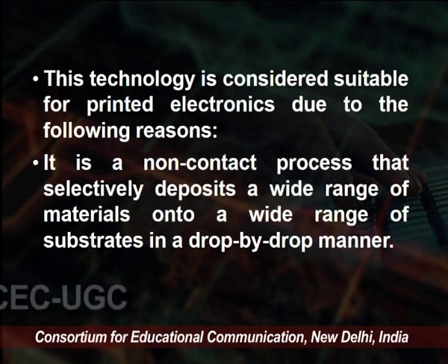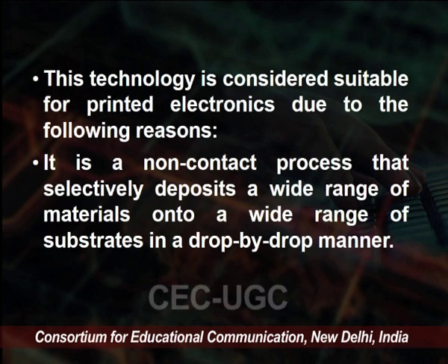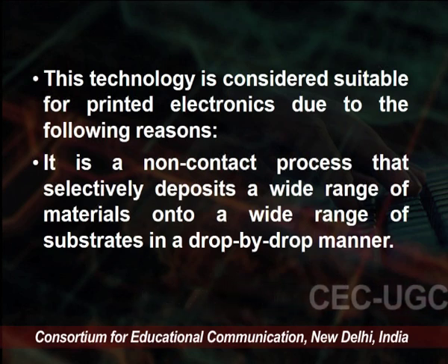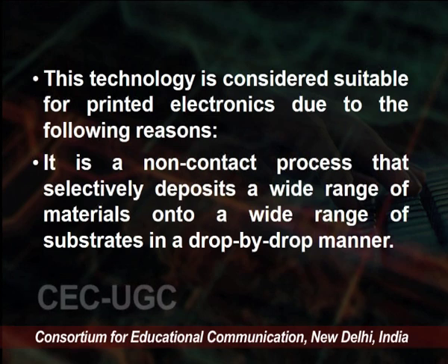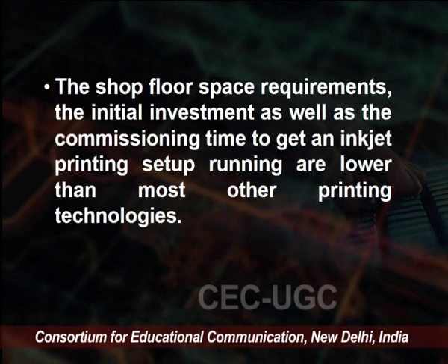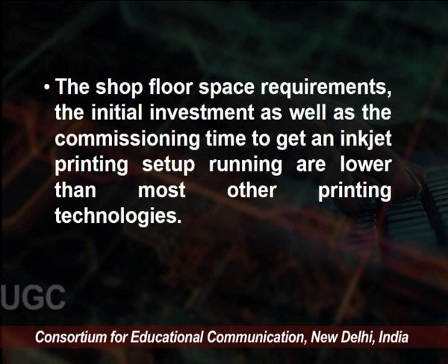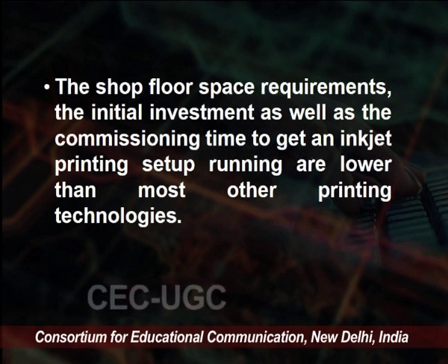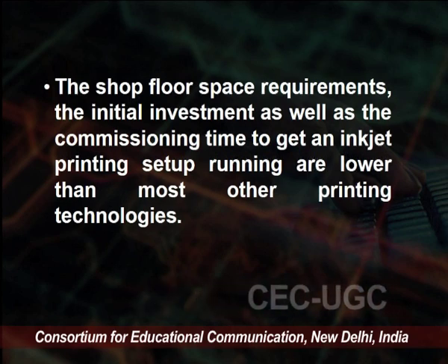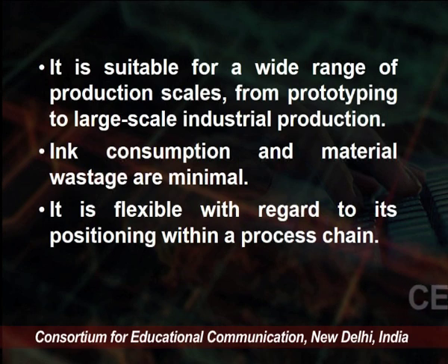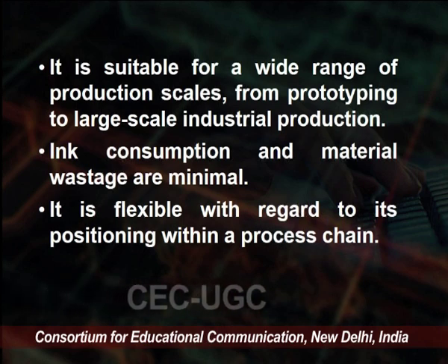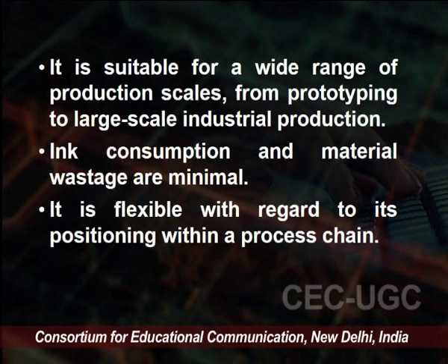Number one, it is a non-contact process that selectively deposits a wide range of materials onto a wide range of substrates in a drop by drop manner. The shop floor space requirement, the initial investment as well as the commissioning time to get an inkjet printing setup running are lower than most other printing technologies. It is suitable for a wide range of production scales, as it is very easy to make one prototype, and then a large number of devices can be printed on the substrate.